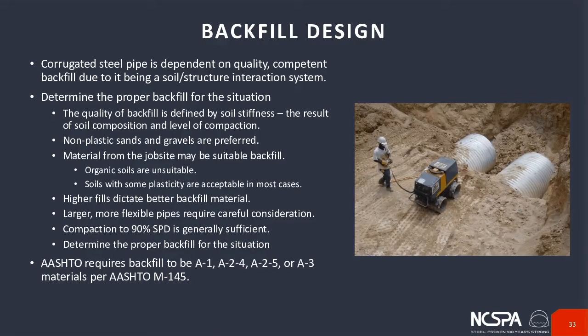Once you get into higher fills, you're worried about the soil load being carried, because it's affected by the quality and stiffness of the backfill. If you have a lesser backfill material, you will generally have less stiffness being carried down and transferred around the pipe in ring compression. So better materials help reduce the loads on the pipe while also providing better support and improving the structural strength.